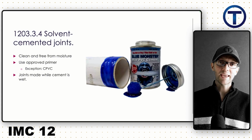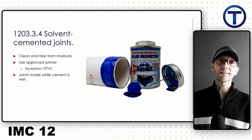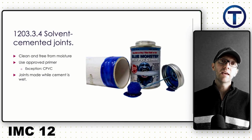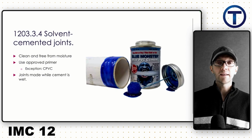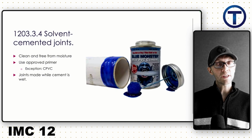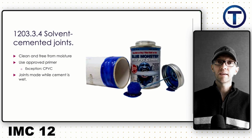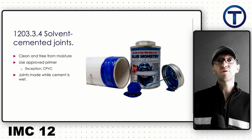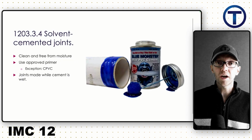If I'm putting mechanical piping in the dirt, I need to work harder to keep it clean. Speaking of keeping it clean or getting it clean, this code states that you should use an approved primer. Now, plumbers, listen closely. When you're assembling drainage waste and vent piping, code says in International Plumbing Code, up until 4-inch pipe, you don't have to use a primer. But is it a good idea?